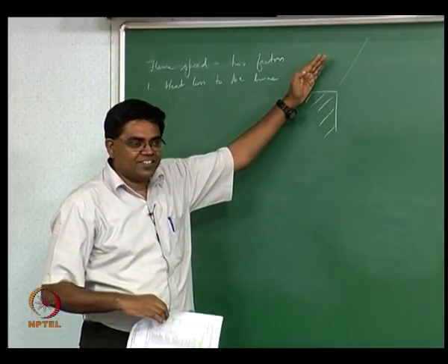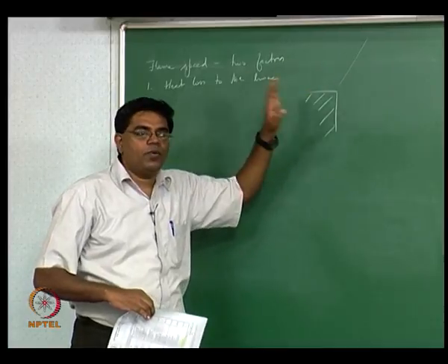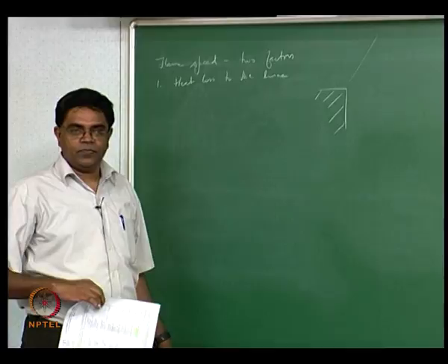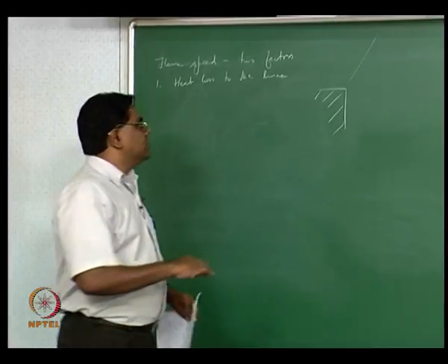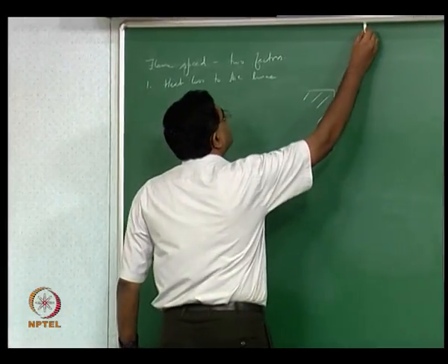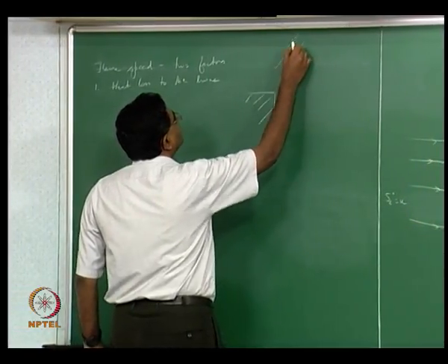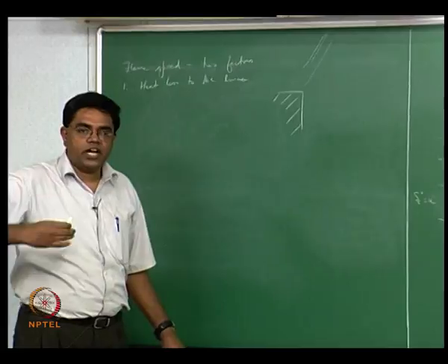You now have to worry about how the preheat zone looks, and how the reaction zone looks. What I know for a fact is, far away from this burner rim I am going to have a certain thickness for the flame, and the preheat zone is going to be thicker than the reaction zone, the larger the activation energy.